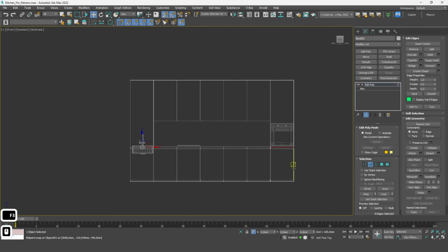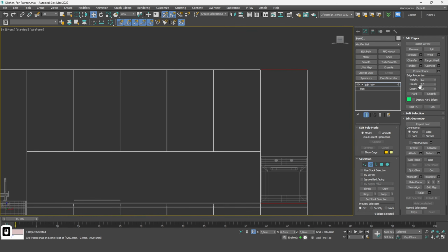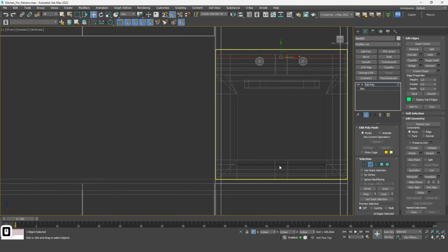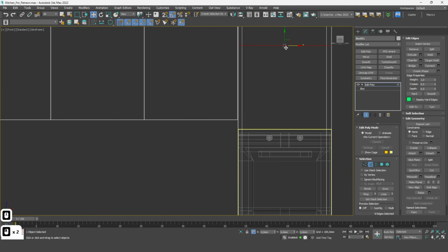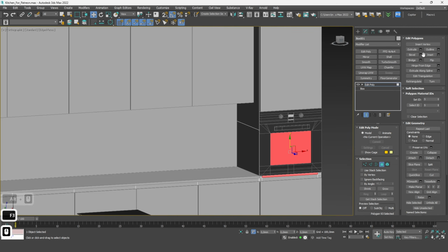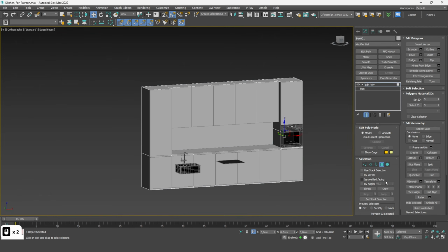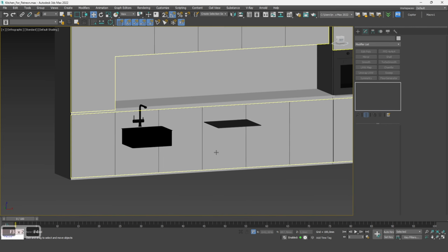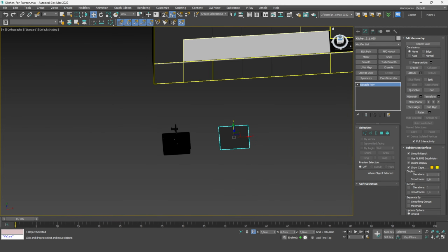Go to the frame, select Edge, select the edges and click Connect. Select 2 lines and place them according to the size of the oven. Select the side edges of the case, click Connect. You can delete the extra one. Place the line along the height of the oven. Select Polygon, click on the part that we have drawn, then click Extrude and press in about 500 to 550 mm. Next, place the stove using the snaps.